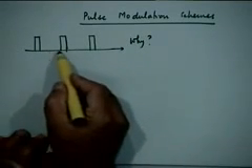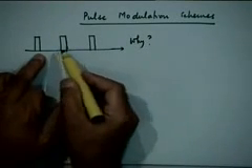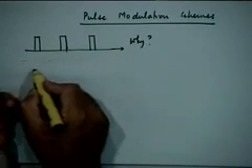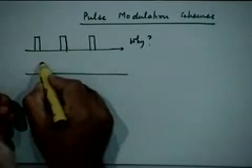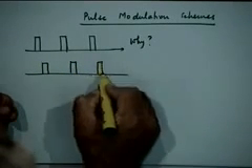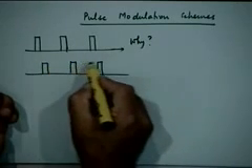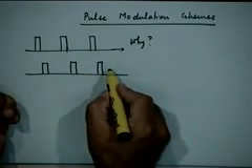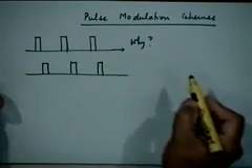In between these two you have vacant time, time which is not occupied by this particular measurement. You could have a second set of pulses measuring the second parameter, and that parameter is transmitted in these slots, and so on.